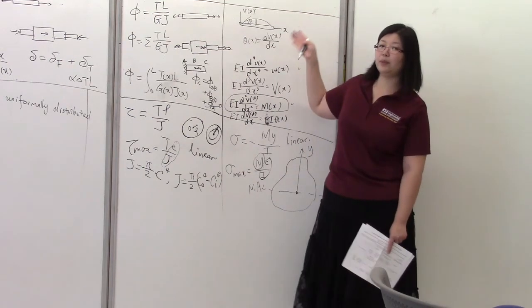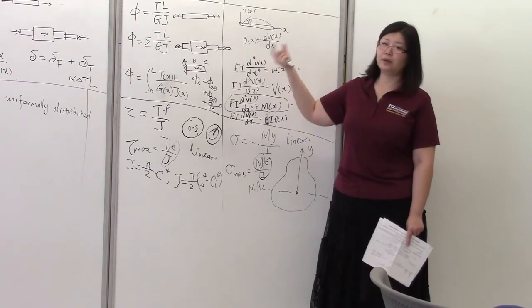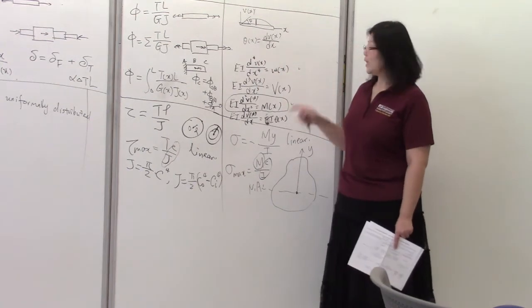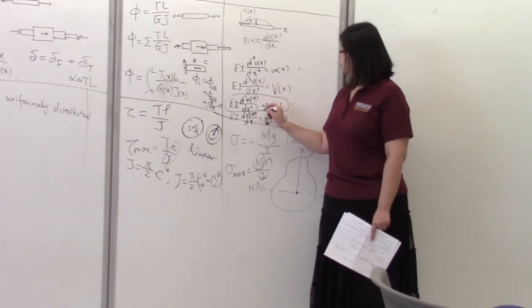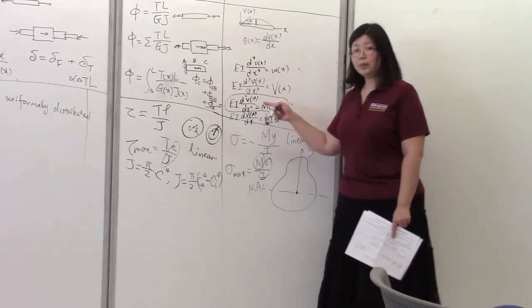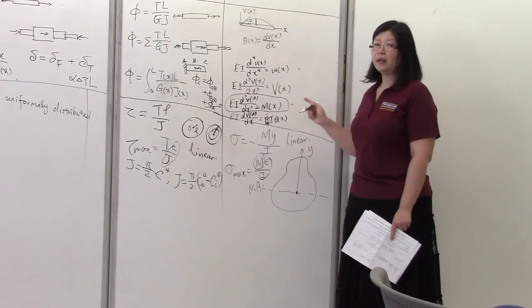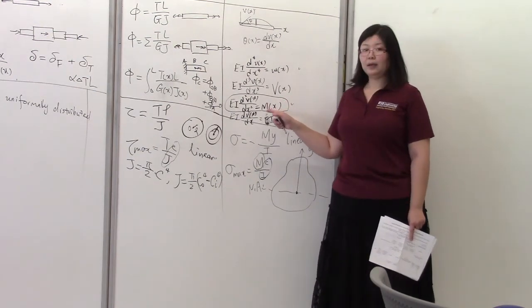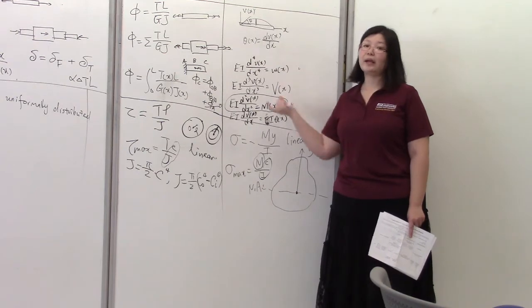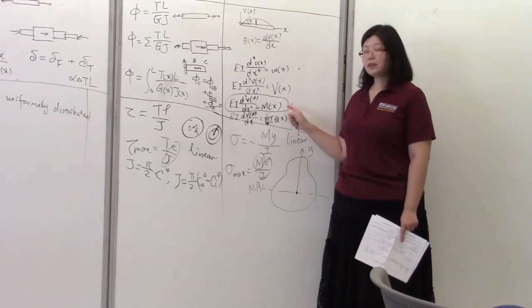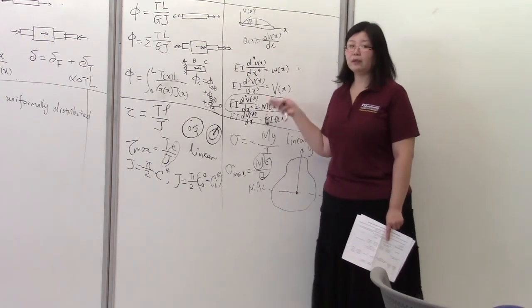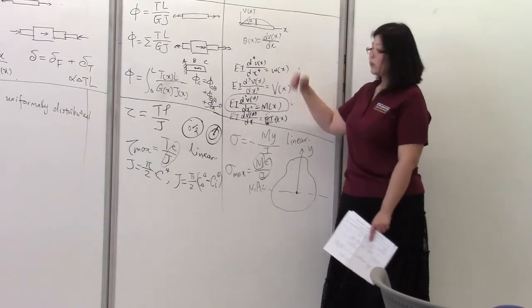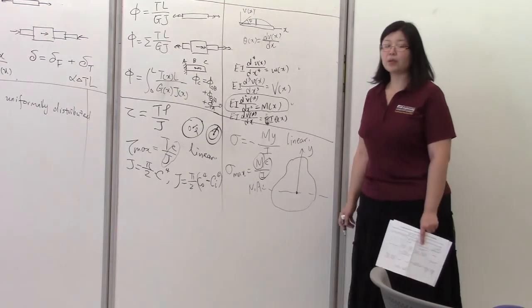So whenever you have an applied point load, applied bending moment, or your distributed load starts to apply or ends somewhere, those are division points. So this should be written for each segment, and then you will need to integrate this twice. So M is the internal bending moment for each segment, and we've already discussed how this is obtained when we were looking at internal loadings. So after you integrate this twice, or 4 times, you would end up having some integration constants.